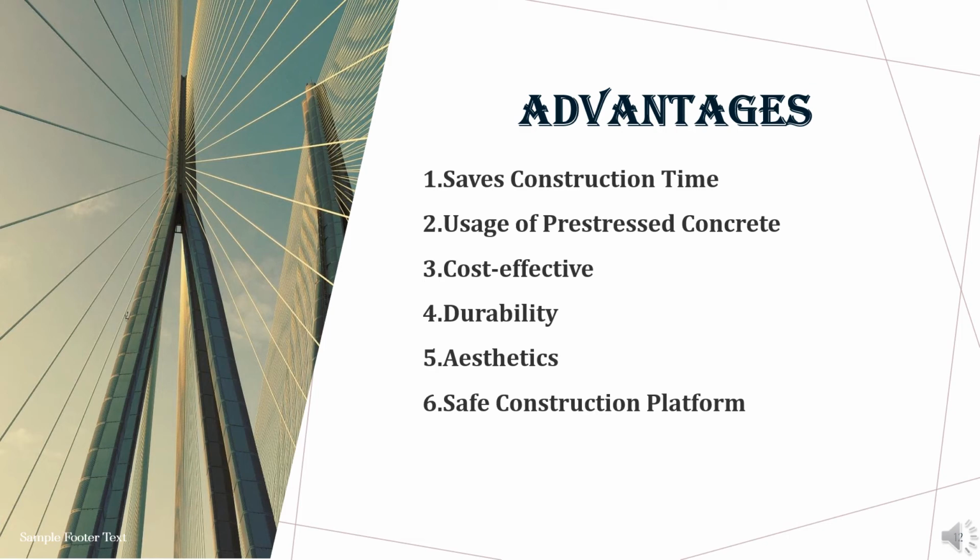Usage of pre-stressed concrete. By using pre-stressed precast, structural materials of high strength and load-bearing capacity can be achieved, which can result in greater clear span, reduced size of the cross-section of structural members, etc. Cost-effective. The simplified construction process reduces the time, increases the productivity, quality and safety and thus the cost is reduced. Durability. Precast concrete structure has a longer service time period and minimal maintenance. The high-density precast concrete is more durable to acid attack, corrosion, impact, reduces surface voids and resists the accumulation of dust.